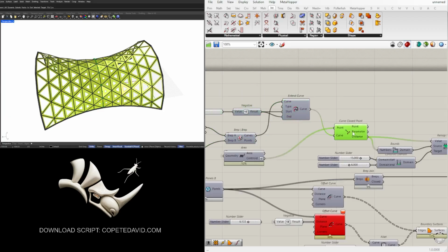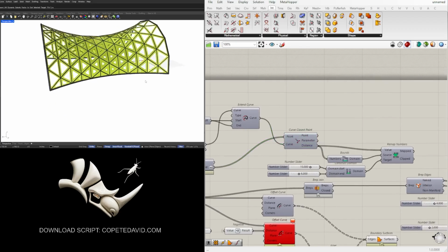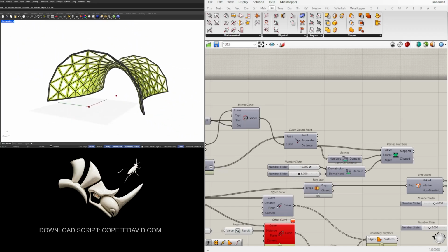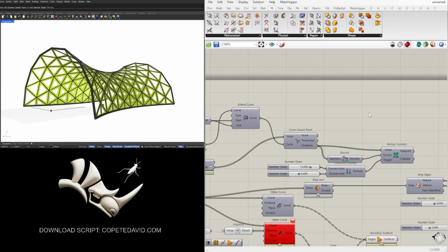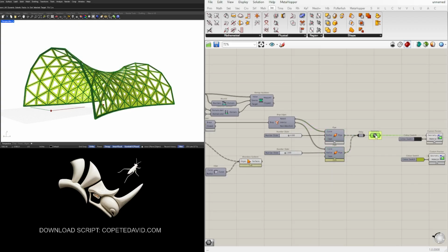Now I'll hide this. I'll hide this. And now let's take this and do a render to see what this would look like. So what I like to do is these two are the outputs and they're both plugged into this one. So one thing I can do is double click here to create a relay and then use a geometry component. So you can know that this is going to be the output, and I like to group it. I have it by default as screen. And now we can hide this because this is now the geometry that we could bake.